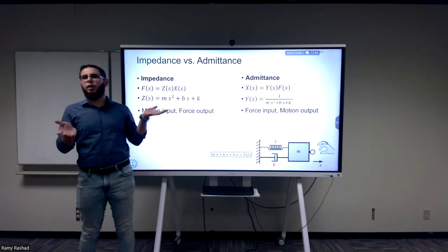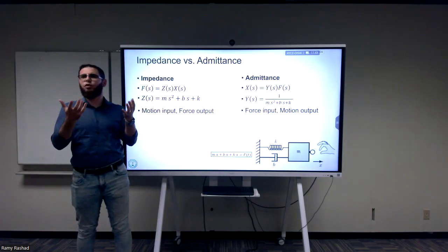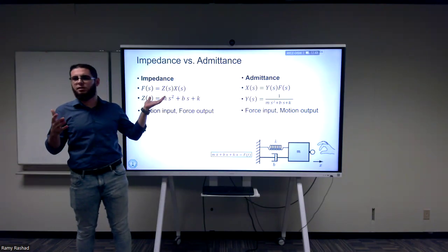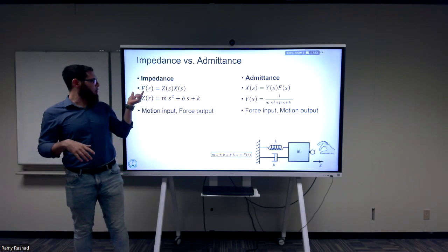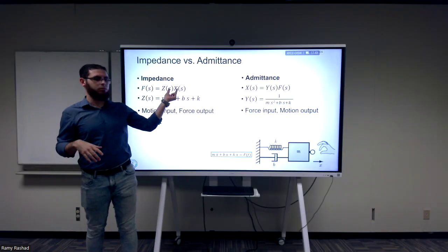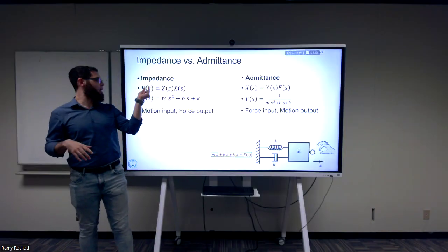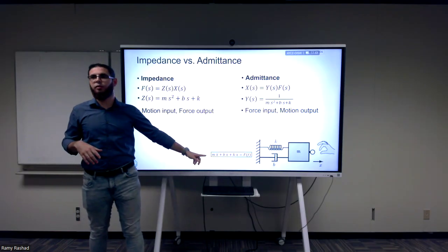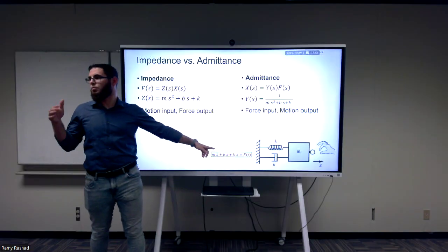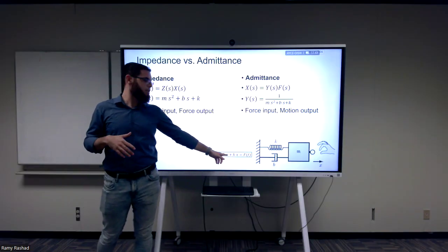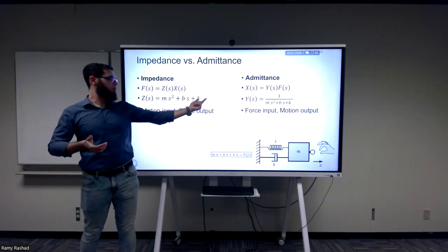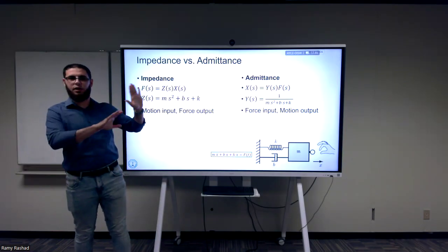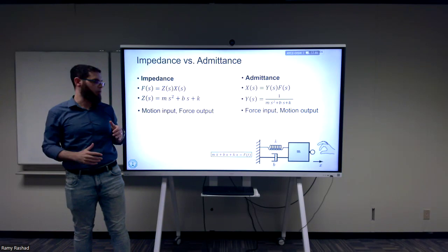So this is also something you might have done before, okay, which is, it's clear what the impedance is, because here we depend on the time, or we depend on the frequencies. If we look at the Laplace domain, then we can rewrite the position of this mass multiplied by the mechanical impedance will give us the force. And this is nothing else than just the Laplace transform of this equation. So the dots are represented by s. So here are two dots, s squared. One dot is the s. No dots, then we just get the variable X of s. Okay, so this is just a reminder of what you know. If you know it, that's okay. If not, this is all just motivation of where we're going.